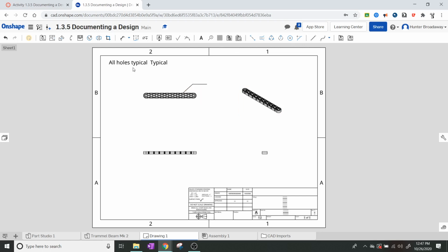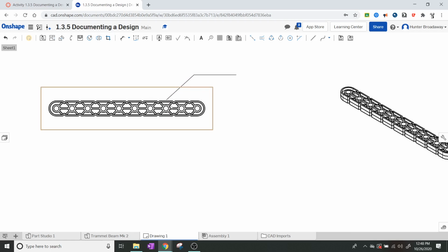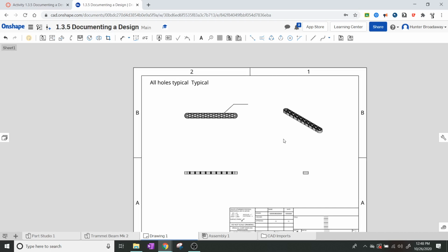But you can link your text and leader lines to show you information. So if you wanted to talk about whether this thing is made of plastic, or the density or things like that, you can include these as well. But leader lines aren't usually dimension lines because they don't give you a start and an end point, but they do normally try to tell you some piece of information about the object. Okay, so if you wanted to mention how this thing on the bottom kind of looks like a TIE fighter wing, you can just say, hey, TIE fighter wing design or something like that. Although in engineering you probably want to be a little bit more specific than that, but you get the idea of how it goes.